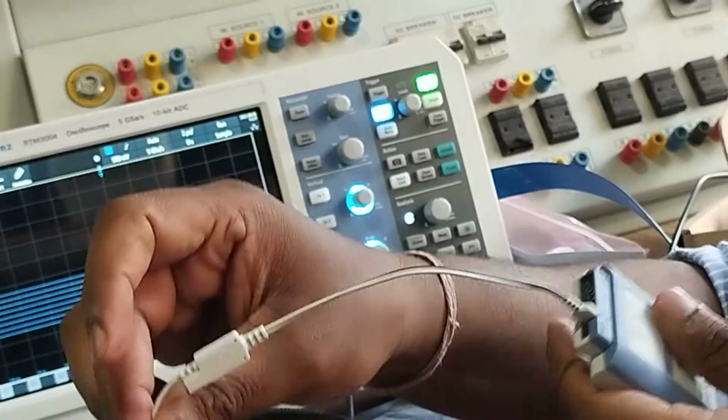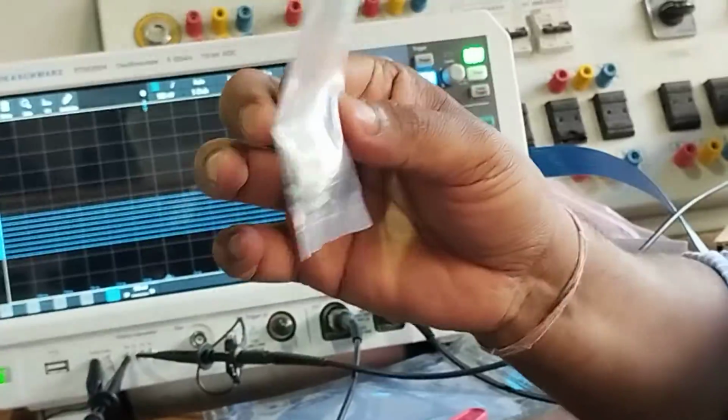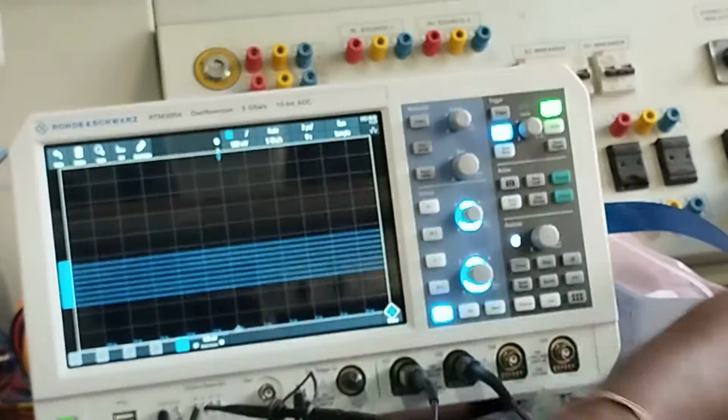On your PCB board, if you have the pins, you can probe directly like this. Or else we have the other clips for assembly components. If you have individual grounds, these are the individual grounds you have to connect at this point. These are the 8 ground cables. If you have only a common ground on your cable, these are the common ground clips you have to connect at this common ground.